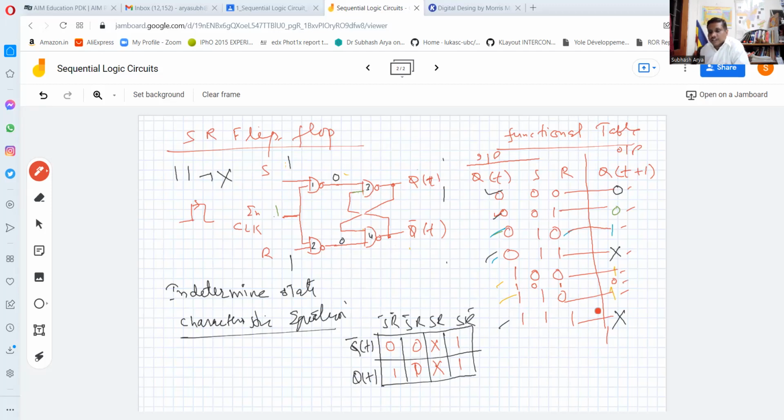You can cross check anytime. Now we want to simplify this K-map. So we can easily make a quad group of 4 ones by considering this dot here as a 1. And in order to include this, we can make a pair of these corner ones by folding this. So let us see what the expression will be.